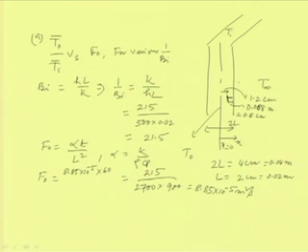By putting the values of the time, we can find out the values of the center line temperature for various times, divided by L square, and we know L is equal to 0.02. So this is 0.02 whole square, because 2L is equal to 0.04. So L is equal to 0.02, and that way we get the Fourier number as 13.28.